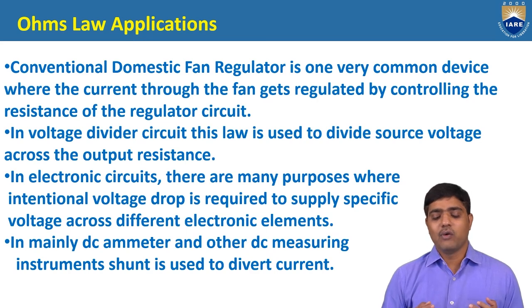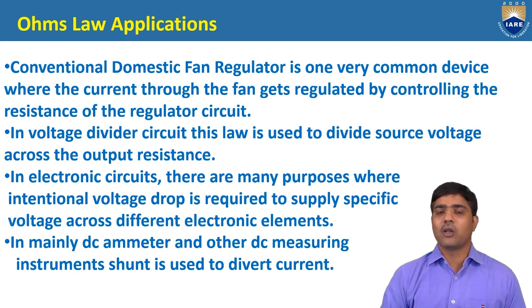Also in voltage divider circuits or in series and parallel circuits, you can apply Ohm's law to find out the unknown values of resistance as well as currents. And not only in electric circuits, in some other electronic circuits and instrumentation circuits also, you can utilize Ohm's law to provide the necessary voltage drop in a circuit. So this is all about resistance and Ohm's law.